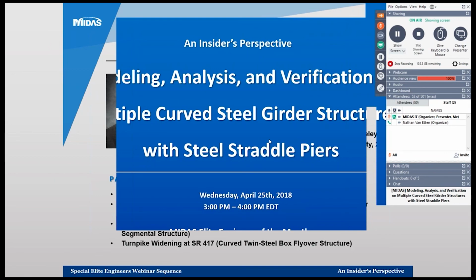As you define more girder sections, you can modify the girder sections along the length of the girder to account for that splay, which I think we consider a tapered section. So if you're trying to create a tapered section, yes, that is possible in MIDAS Civil using the wizard. And there are a couple of great tutorials on YouTube for how to do that.